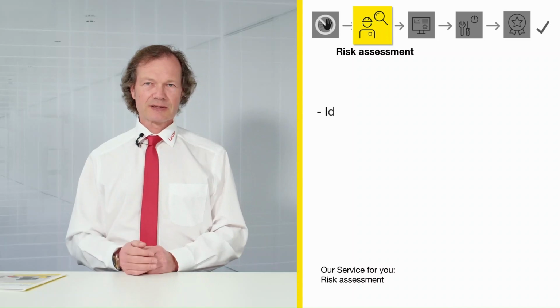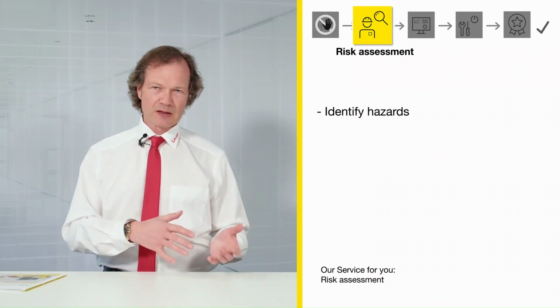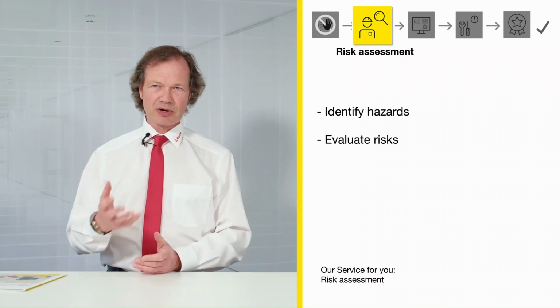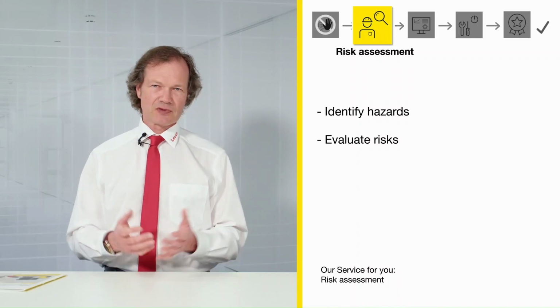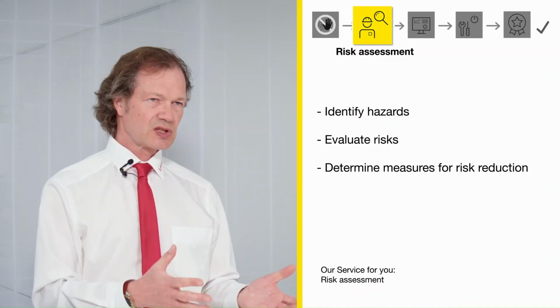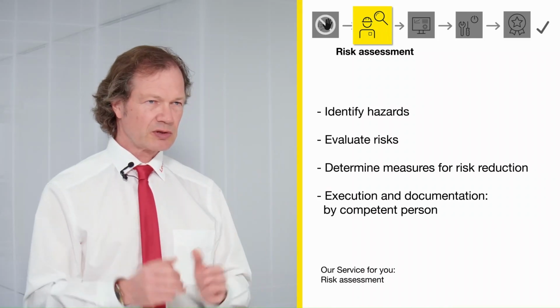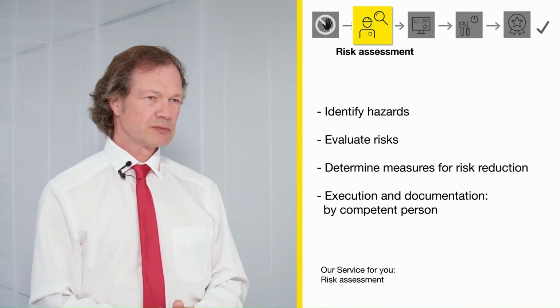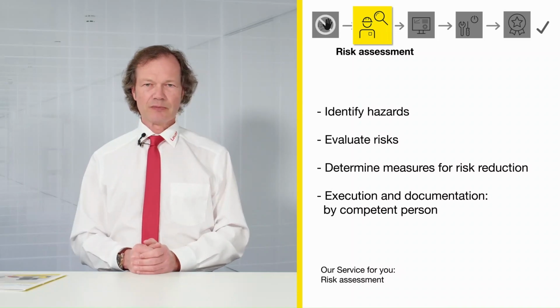First, all hazards have to be identified. Then, the risk caused by the hazards are evaluated, and finally, the measures for risk reduction are defined. The risk assessment has to be executed and documented by a competent person. Let's take a look at an example.